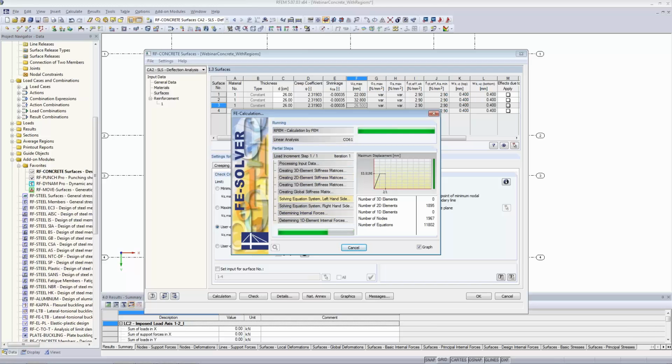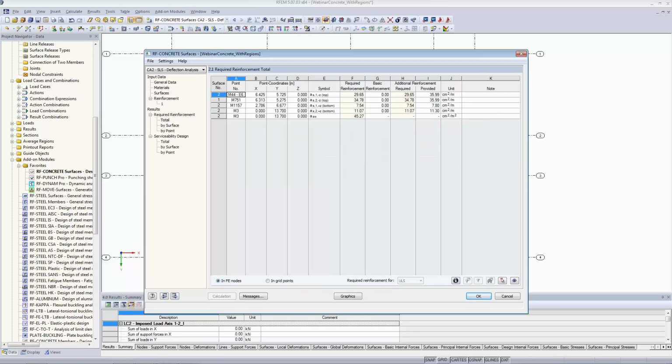You could, for example, superelevate the concrete formwork about 30 millimeter. You could also increase the thickness of your surface. That's what we are going to do. And the worst case would be to change and increase the reinforcement definition. The worst case, because this was quite a bit of work we had.